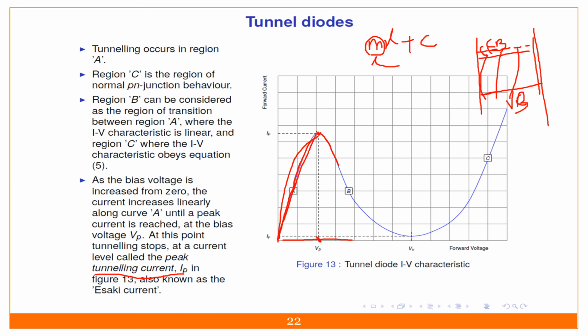If your electrons are shifted to the third band, then what will happen? Their drift velocity is decreasing. If the drift velocity is decreasing, then the resistance is going to be increasing, and if the resistance is increasing, then the current will also be decreasing. From that point, the electrons move from the conduction band to the third band, which is a small distance itself. So the current is caused to decrease.